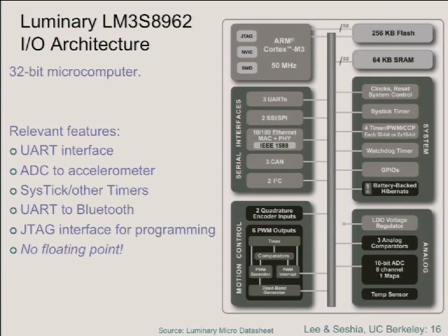Then you read back the entire state of your processor, and your software takes that sequence of several thousand bits, figures out which ones correspond to this register, which ones correspond to that register, and so on, presents that all in a nice GUI to you, showing you what the state of the registers of the processor are, and then allows one more cycle to execute, and then reads back the state of the processor, and so on.